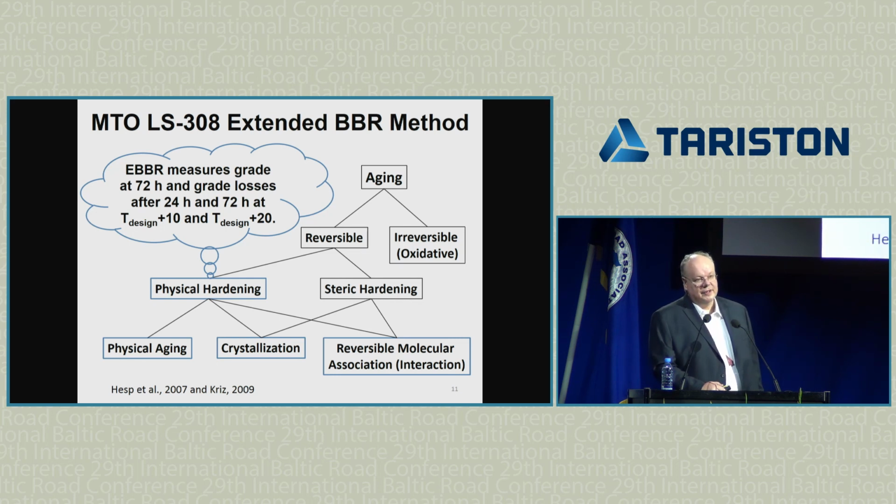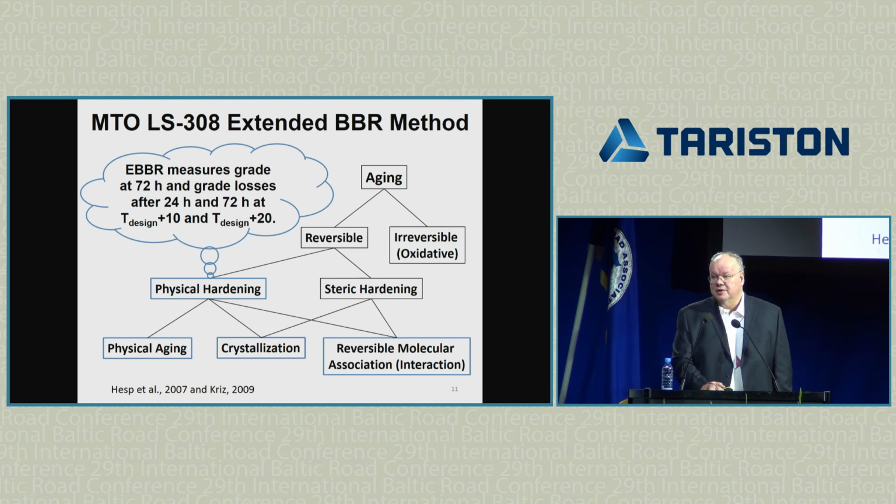It measures the physical hardening tendency when you store a sample at low temperature, and for 3 days you lose your grade, or not. We now have samples that don't lose any grade. Good quality naphthenic crudes produce good quality asphalts.